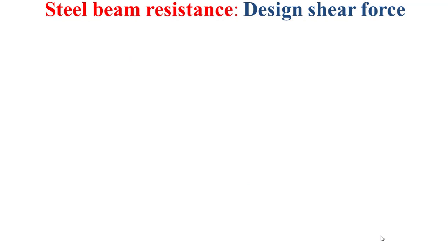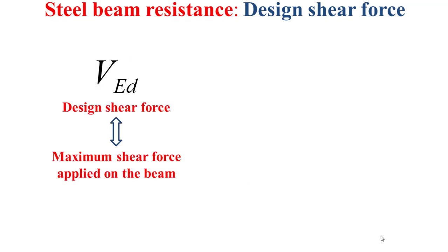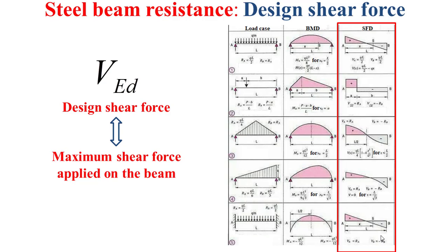It's to note here that the design shear force VED is associated to the maximum shear force applied on the considered beam, and it can be determined based on the table that you see now in this slide. You can notice in this table that the applied shear force depends on the load case. This table presents 5 load cases, and there are other tables presenting other load cases.